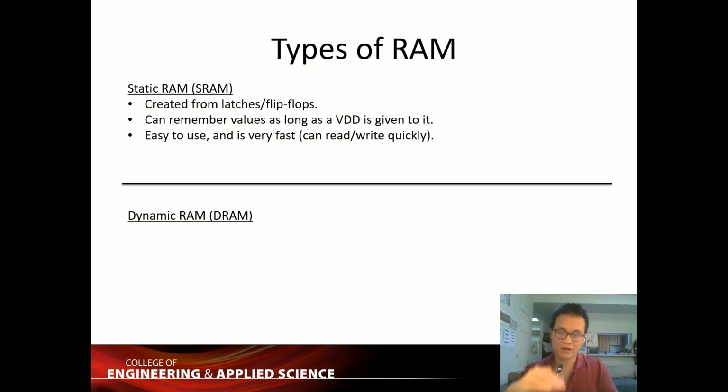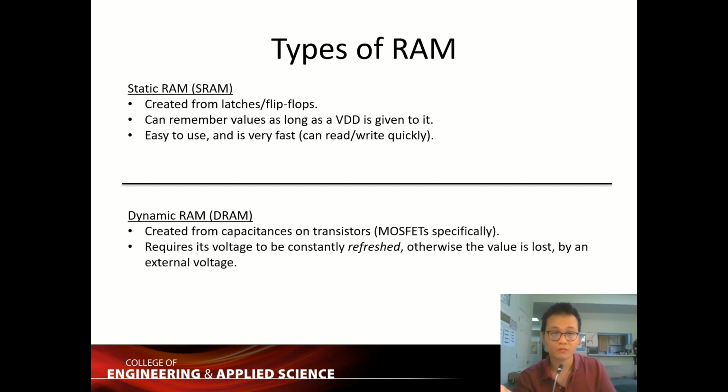So you have 3 layers there. If you remember your electronics 1 class or your circuit class, a capacitor is basically two metal plates with a dielectric in the middle, right? So actually, when you create a MOS transistor, you can create some capacitor effect. So you can store the information in terms of electric charge, provided by the MOS transistor.